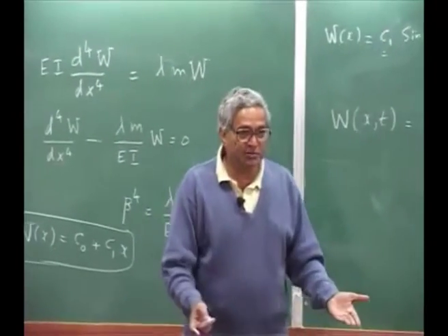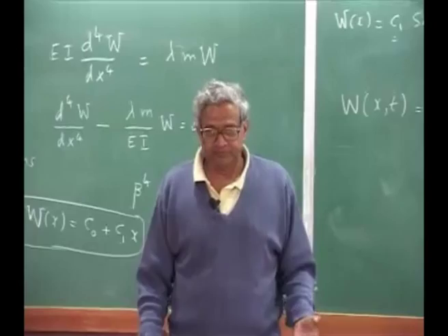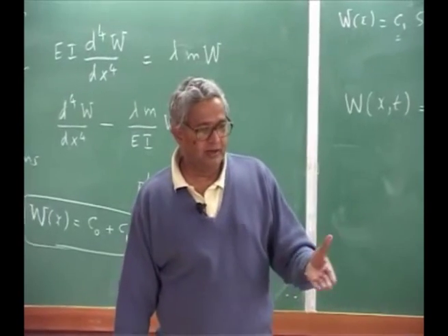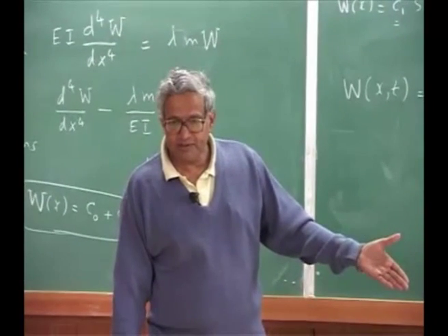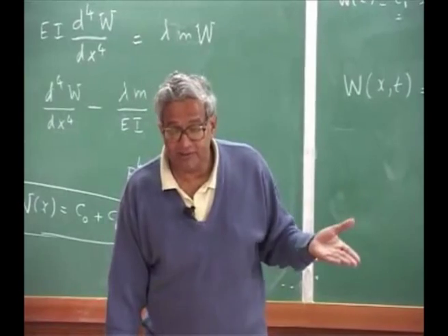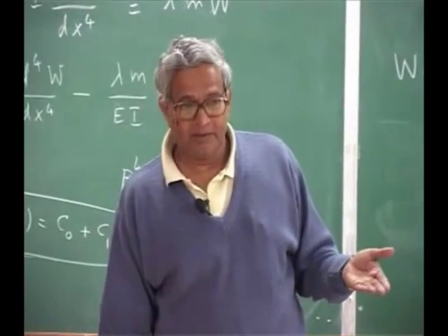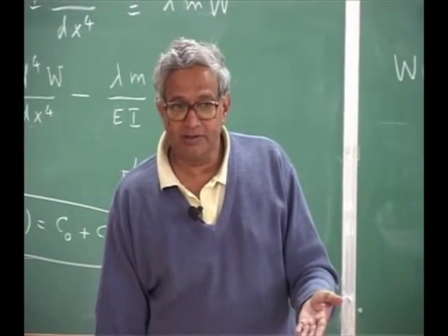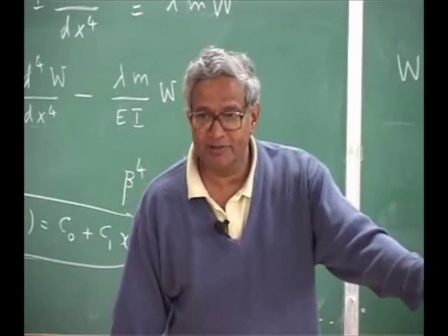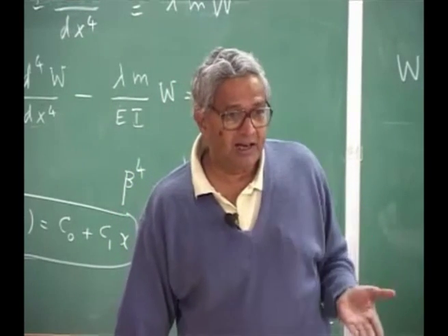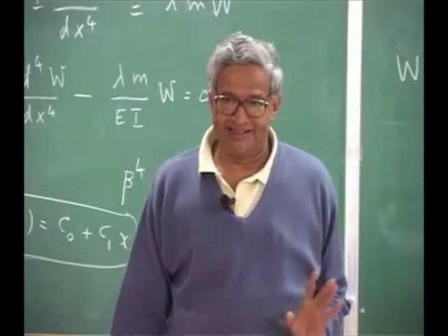The assumed mode shape may not satisfy the equation, but you can at least make sure that it satisfies the geometric boundary conditions, which makes them admissible functions.